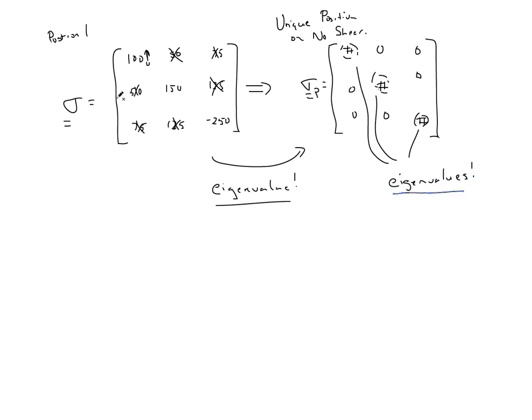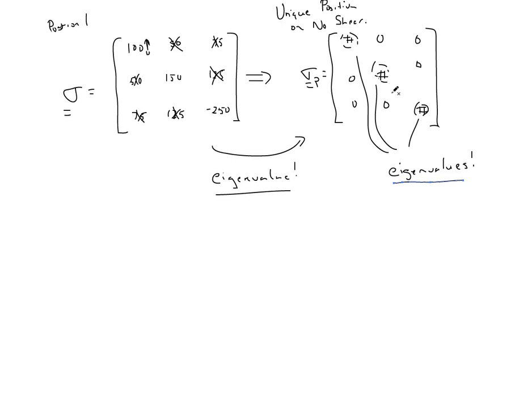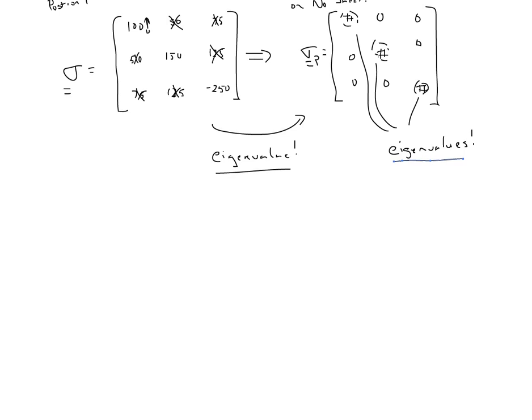So if you can take this matrix and solve for its eigenvalues, you can determine what these stresses are here. And they end up being very, very important for the material properties, because this tells you what happens in the zero shear condition.